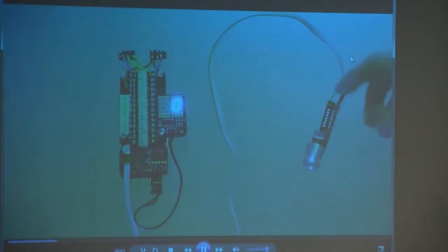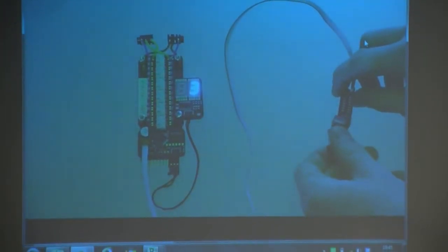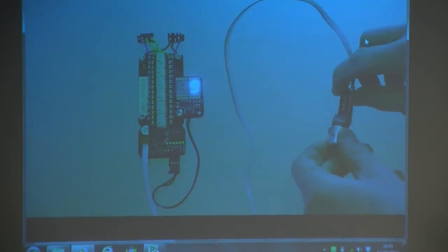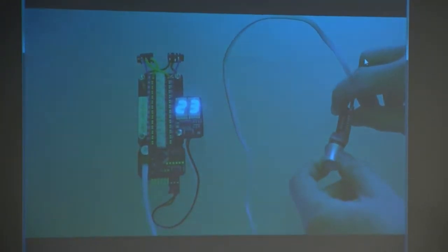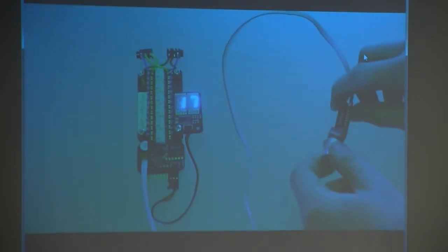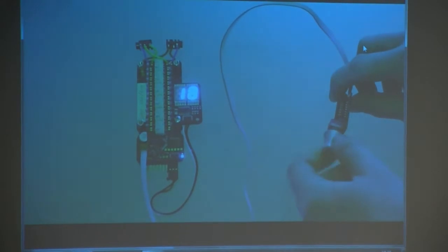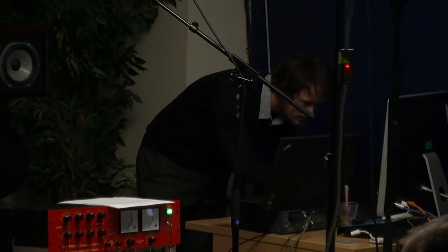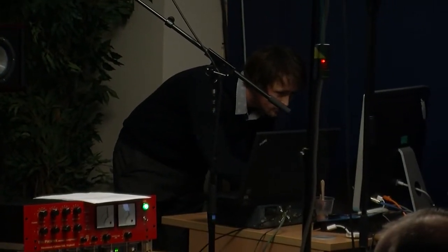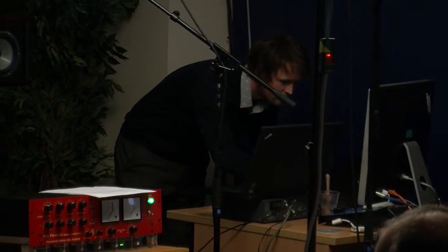This potentiometer is connected to a microprocessor, sending a serial communication to the relays, which are really then just implementing a ladder network. This little display just shows where it's at, and we're now at the stage where we can start plugging audio into it and making sure it works properly. We've got some of these you can have a little look at afterwards.